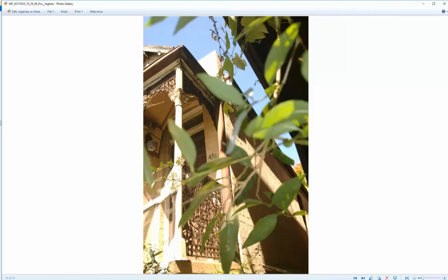That's the better way of doing it rather than have... So instead of putting a downpipe over here, they put a gutter there that takes the water from that side probably to this side and then around. But that's not the correct way to detail it. Yeah, but you'd have one there anyway for that other roof, so that's fine. That's a better way to do it, because the other roof needs a downpipe anyway. So that's what I would have done.